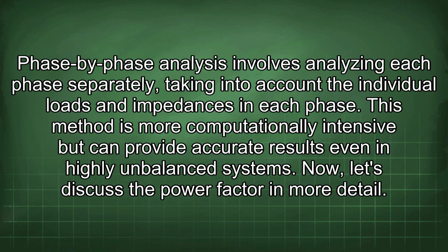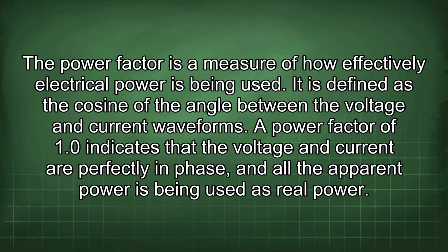Now, let's discuss the power factor in more detail. The power factor is a measure of how effectively electrical power is being used. It is defined as the cosine of the angle between the voltage and current waveforms. A power factor of 1.0 indicates that the voltage and current are perfectly in phase, and all the apparent power is being used as real power.